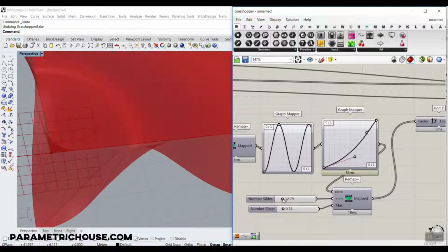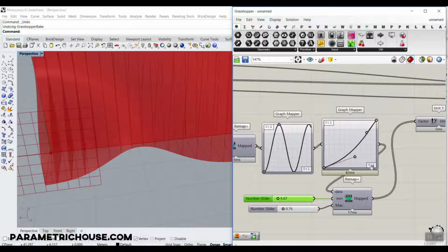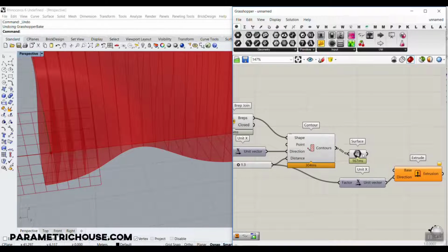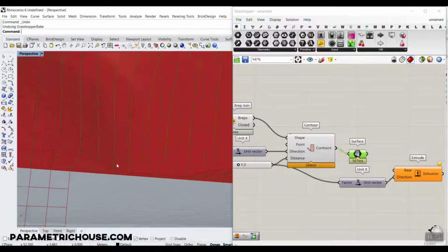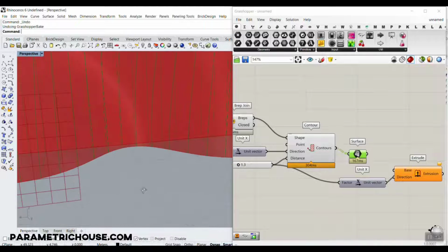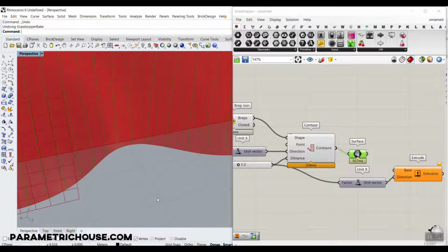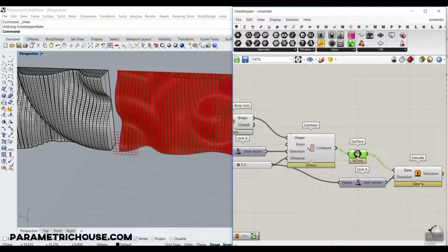Just try to play with that to make a complete correct thing with those curves, so you don't have problems. As you can see, that's going to give you the correct one. So you can just skip that. If you want, you can go to Rhino and make that surface an extrusion, but remember, you have to have the correct thing to make that surface happen, and don't run into errors or warnings. So that was the tutorial of how you can make a complete parametric wall.